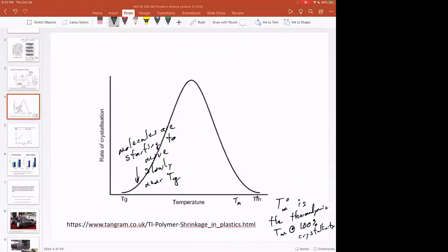And so you've seen some of the YouTube videos of supercooled water in a water bottle. So you have a water bottle that's really cold. It's been in the freezer for a long time, and you open the cap and the whole bottle crystallizes at once very quickly. So that kinetics of water crystallization is fast because that's a small molecule. And so small molecules crystallize quickly. As soon as you cool iron down below its melting point, it crystallizes rather rapidly. I mean, crystallization kinetics are known for many, many different materials, and they're rather fast for small molecules or metals.